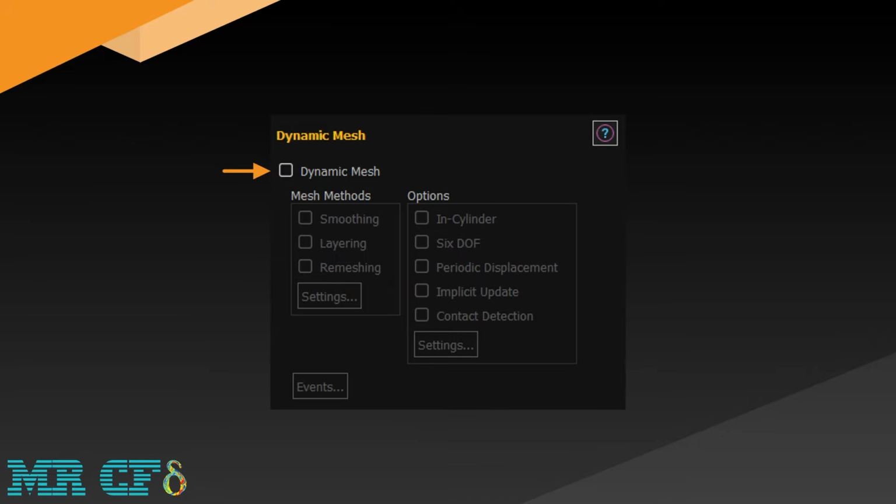Notice that you can find dynamic mesh on the left side of the Fluent workspace. In the upper left box of the dynamic mesh model settings, we specify the mesh update methods. It means to specify how the meshing of the model and its cells are updated when the computational area or its borders are displaced or deformed due to the use of dynamic mesh.